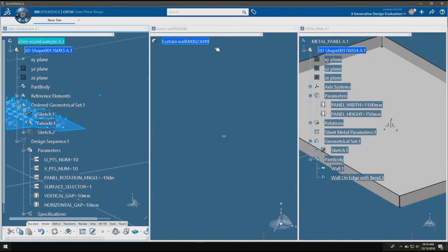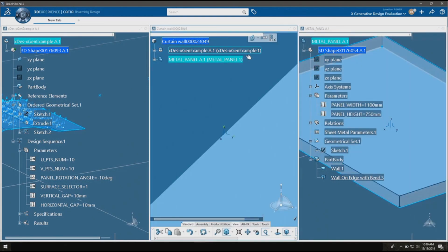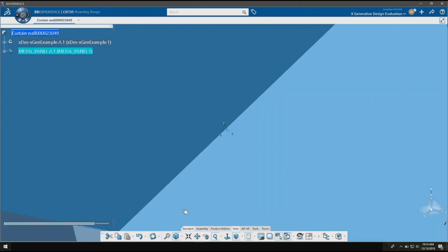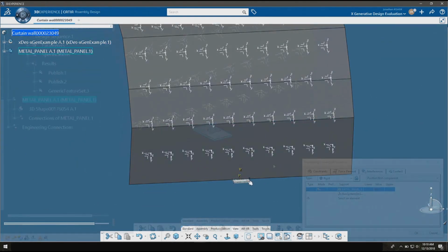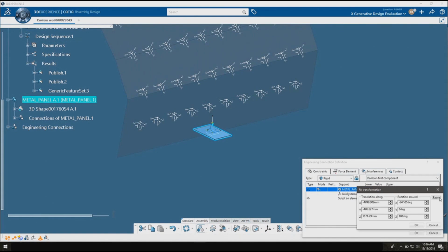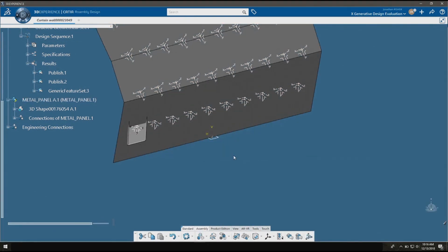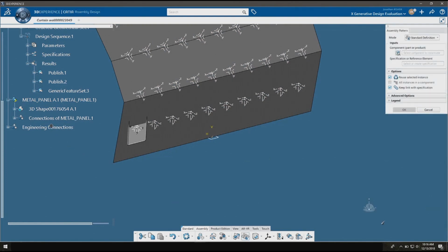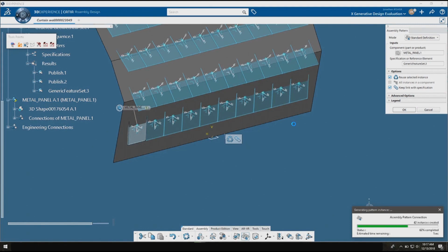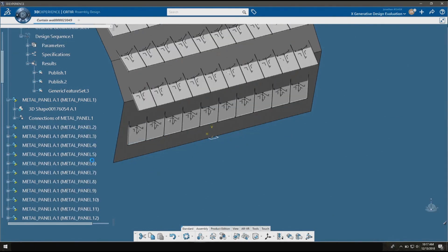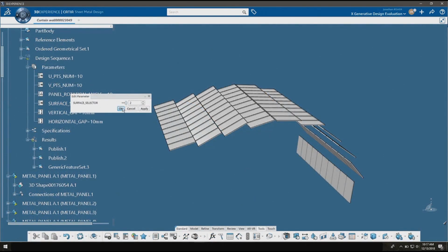And now I'm going to create a CATIA assembly, a curtain wall assembly. So I'll input my X Design and X Generative Design model. I'll input my sheet metal panel, and I assigned the width of this sheet metal panel based on the rectangle sizes from X Generative Design. I can do an assembly constraint to position my sheet metal panel in place, and do an assembly pattern to replicate that panel across all of the axis systems in my model.